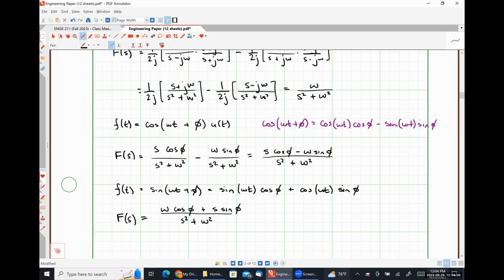Thank you. Gabriel. Fair game, absolutely. So as long as you can remember how to transform from a transformer into the T model, the energy storage relationship should be very straightforward because it's just the energy stored by each inductor, add them all together. So as long as you can figure out what currents are flowing through each inductor, you can derive it in literally seconds.